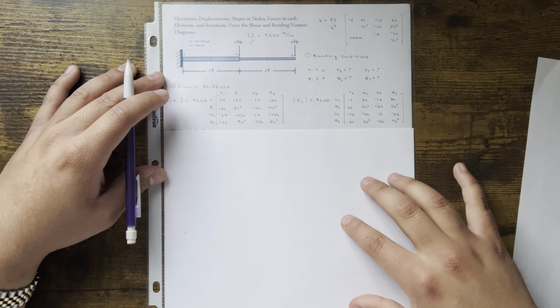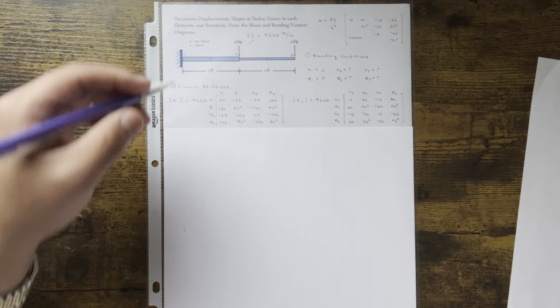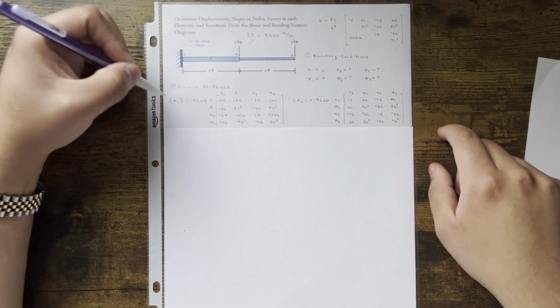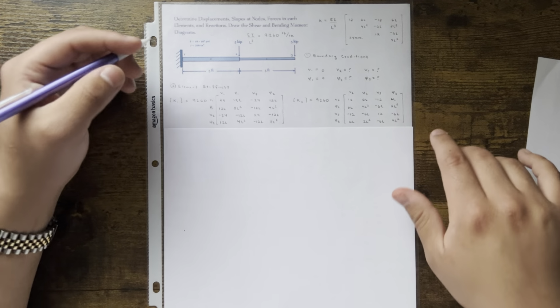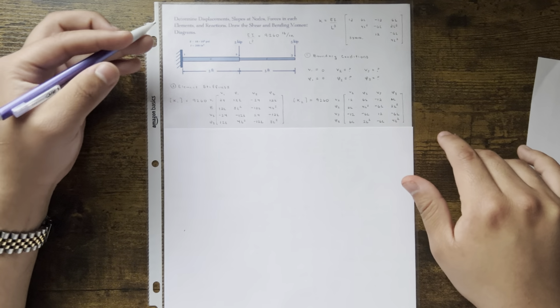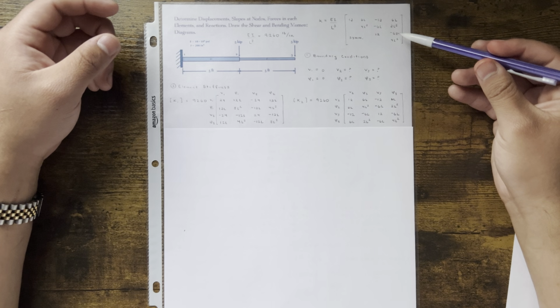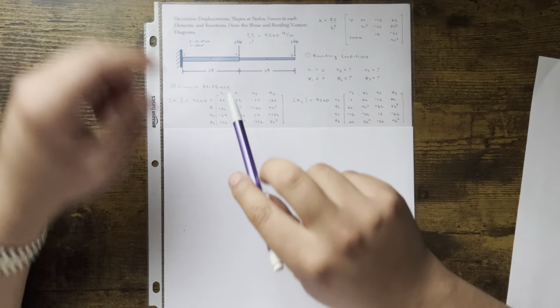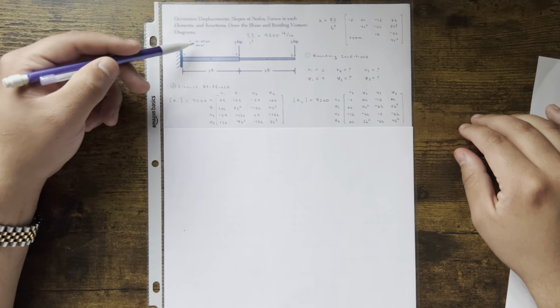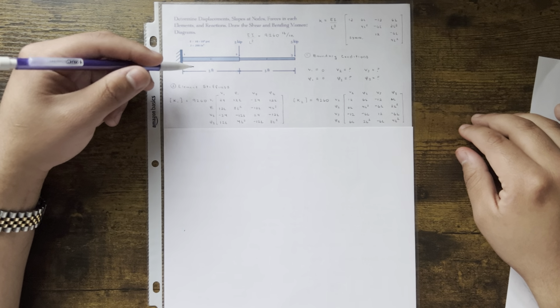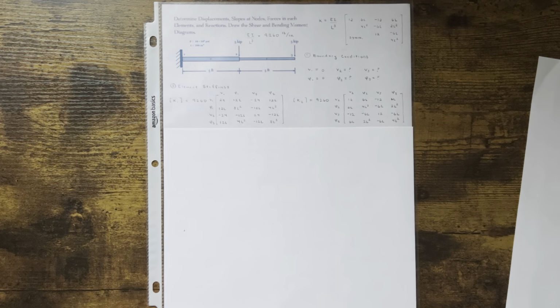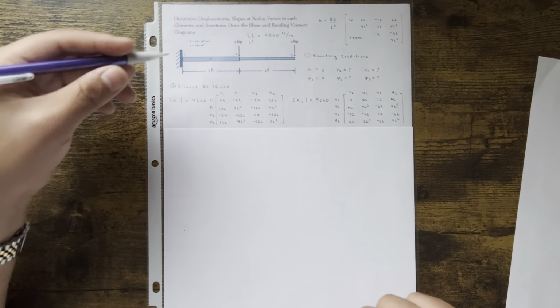Let's go there. Because this one has twice the moment of inertia, it's better to separate it out so you can see it. This is what happened, look. Initially, we're using this stiffness for each element, right? But because one is twice as big as the other, in this case, element 1 is twice as stiff as this one, the magnitude for element number 1 is going to be 2 times, if that makes sense. Okay, so just give me a second. This is what I'm trying to tell you guys.